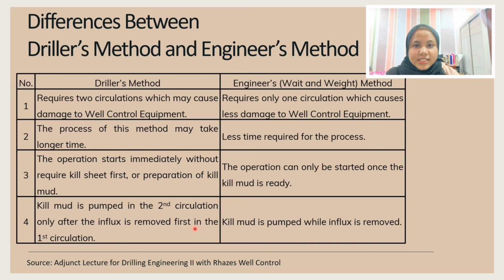Next, as mentioned just now, in driller's method, the kill mud is pumped in the second circulation after the influx is removed in the first circulation, which is different from the engineer's method, as kill mud is pumped whilst influx is circulated out up the annulus.